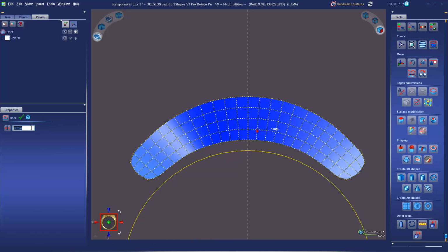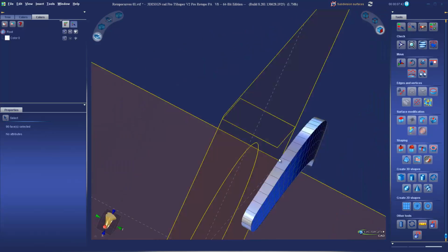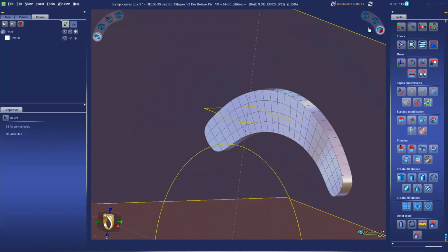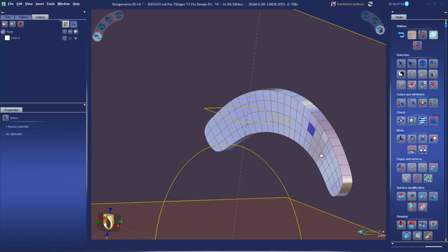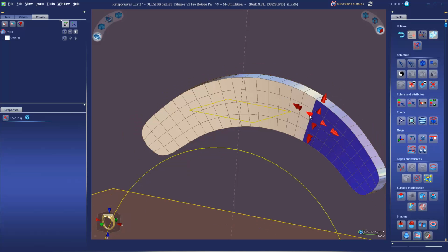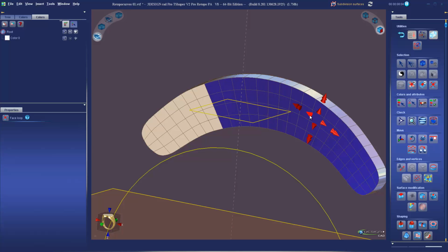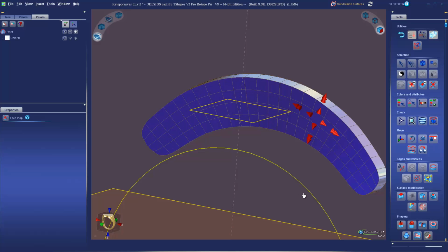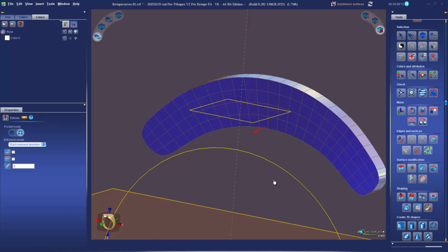This time I'm going to go outside the ring, so I'm going to make a cutter. So I'll do a +1 millimeter. Validate that. Gives us our cutter, and then to select the outside, I just need to select this entire group of faces. So I'll use our face loop and quickly select in that direction, and then quickly extend the selection in either axis. Something like that.